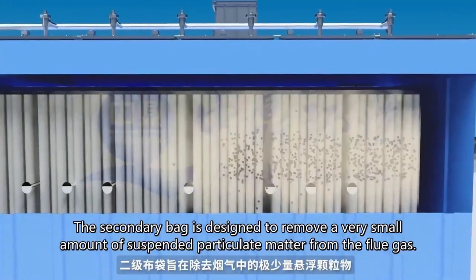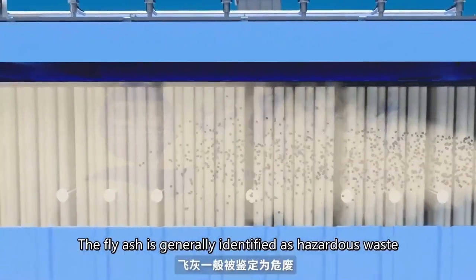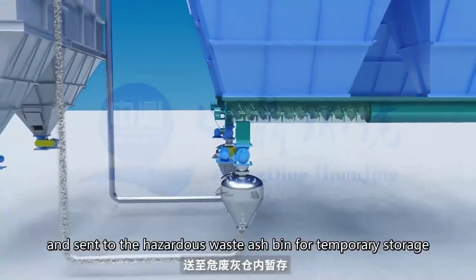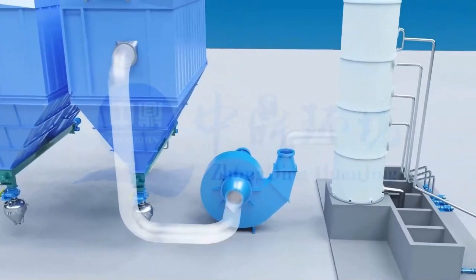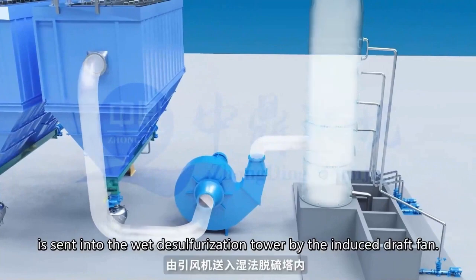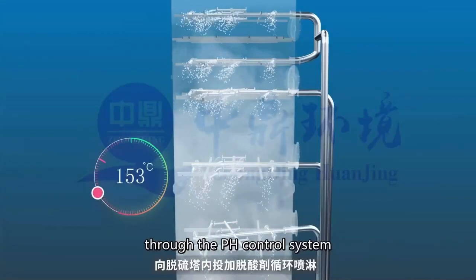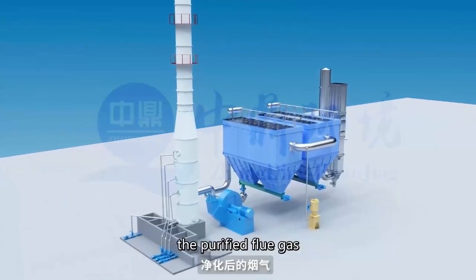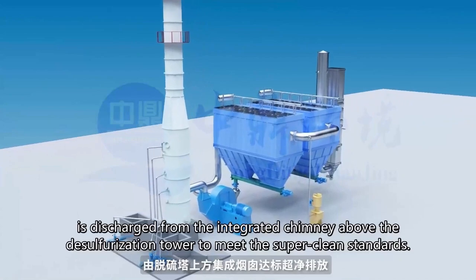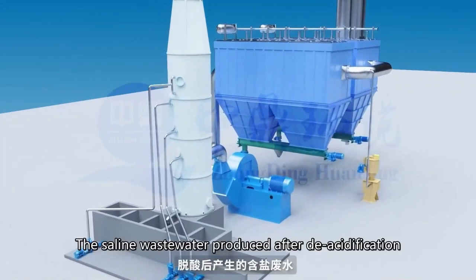The secondary bag filter aims to eliminate very small particles in the flue gas. The fly ash is generally identified as hazardous waste, sent to the hazardous waste ash warehouse for storage and treatment. The flue gas from the secondary bag filter is sent to the wet desulfurization tower by the induced draft fan, where the desulfurizer is continuously sprayed to achieve final desulfurization. The purified flue gas is emitted via an integrated chimney above the desulfurization tower, meeting ultra-clean emission standards.